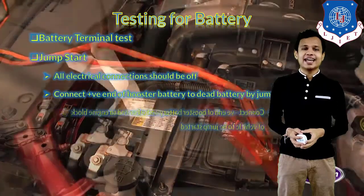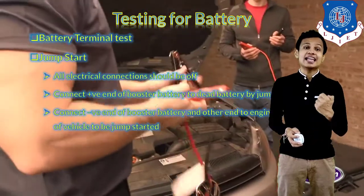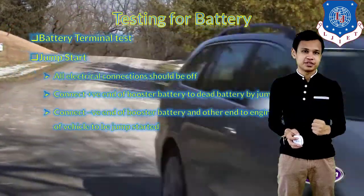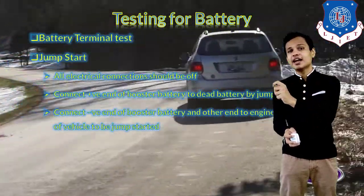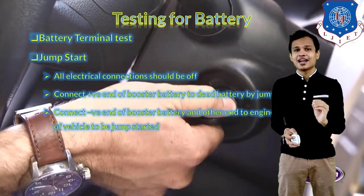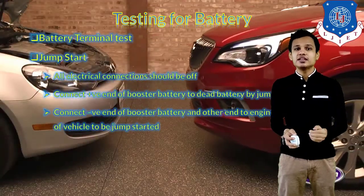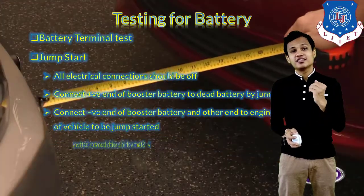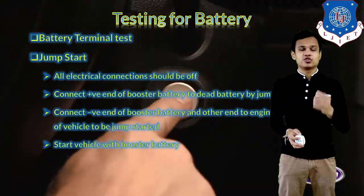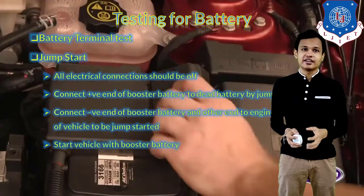Next, we will connect the negative end of the booster battery to the engine block of the vehicle that needs to be jump started. Right, so the negative end of the booster battery will be connected to the engine block, where the power will be transmitted for the negative cable. Next thing that is required is to start the vehicle that has the booster battery. Right, so the vehicle in the starting condition will be started.